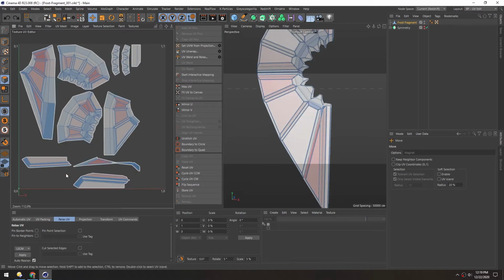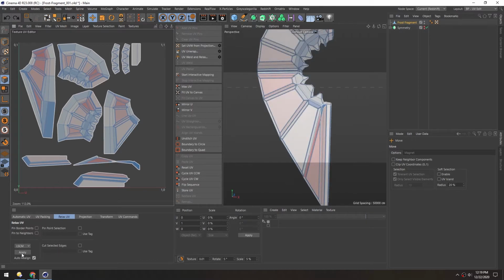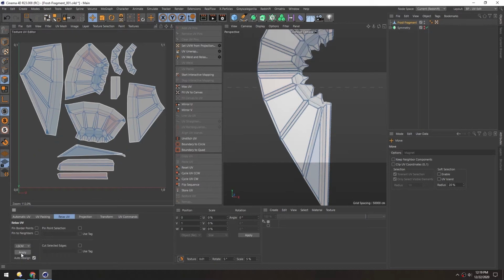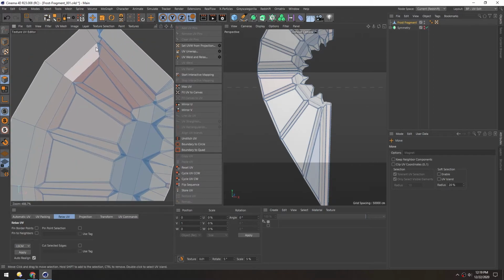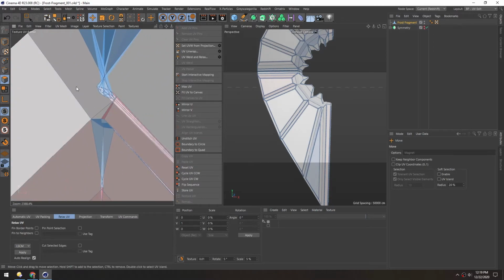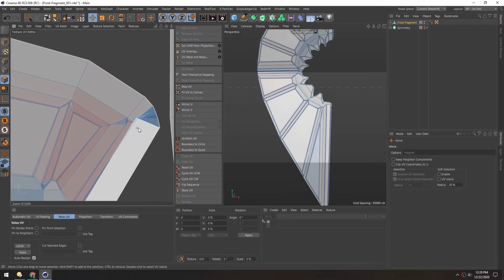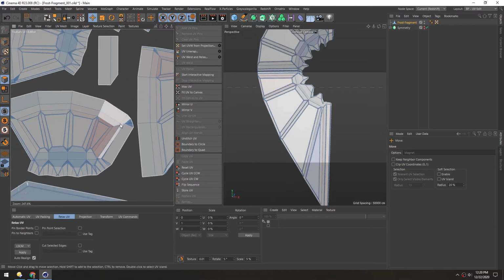Now once you have things broken up fairly well, you can go to the Relax tab, and then click Apply down here. And keeping Auto Realign checked is nice, because then it'll rearrange everything. And you can click it a few times just to keep relaxing it. And it looks like that did a decent job. Although, looks like there's some overlapping here, which is not good. Yeah, I think the relaxing did a bunch of damage.